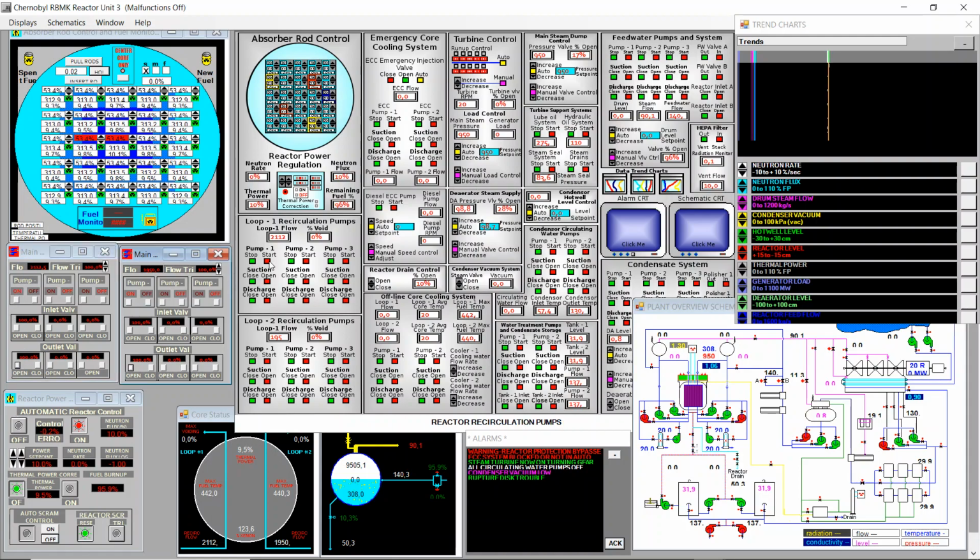I remind you, one out of 3 pumps on in each one of the primary loops. I call them primary loops; here they are just called loop 1 and loop 2. These are like the core flow in the boiling water simulator from Acme. So this just recirculates water within the reactor and passing through the drum, but this is always liquid water. This recirculates water to assure the reactor is always with liquid water, not with bubbles.